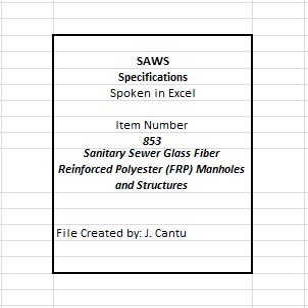3. Dimension. Manholes and structures shall be a circular cylinder, reduced at the top to a circular manway not smaller than 30 inches inside diameter. Manholes and structures shall also be produced in whole foot increments of length, plus or minus 2 inches. Nominal inside diameter shall be 48 inches. Tolerance on the inside diameter shall be plus or minus 1%. The minimum wall thickness for all FRP manholes and structures, all depths, shall be 0.50 inches or as recommended by manufacturer.